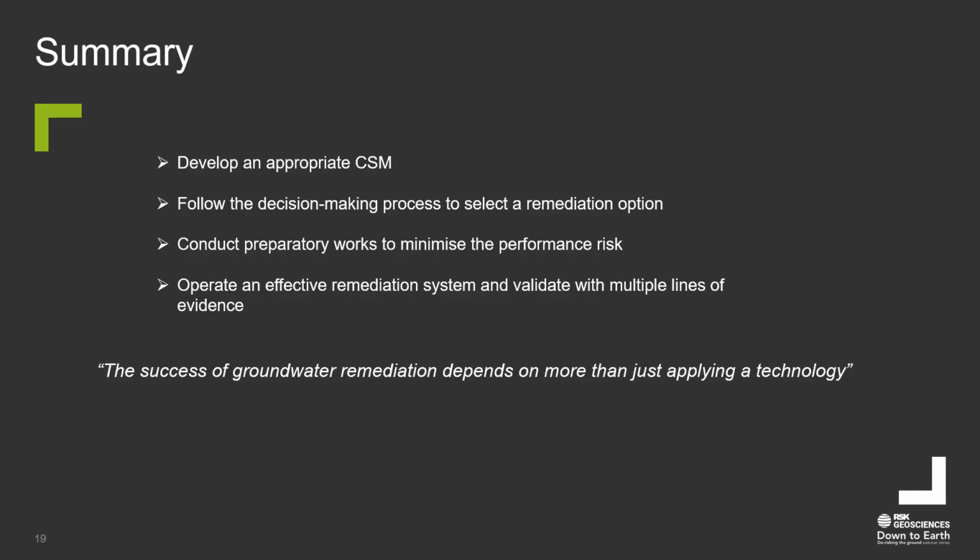As a summary, when it comes to groundwater remediation, develop an appropriate CSM and then follow the decision-making process to select remediation options. Then conduct preparatory work to minimize the performance risks, and finally operate an effective remediation system and validate the success of the remediation with multiple lines of evidence. One important thing to remember is that the success of groundwater remediation depends on more than just applying a technology at the site. That's all I have to say today, thank you very much for listening, and I'm happy to take a question if there's any.